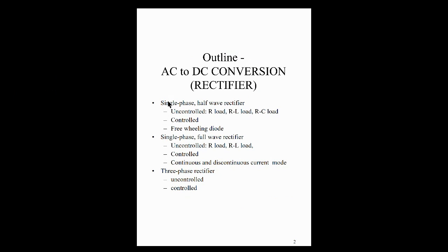For the single phase, right, there are three main headings that we'll be focusing on: uncontrolled, and that's for resistive load, resistive and inductive load, resistive and capacitive load. Right, when we say uncontrolled, based on our last class, this is referring to the diode, right? That's uncontrolled rectification.